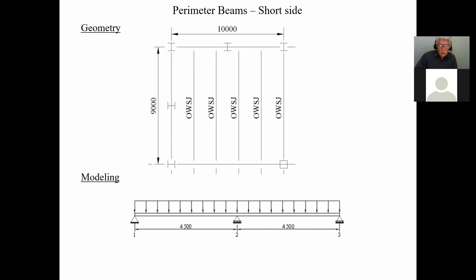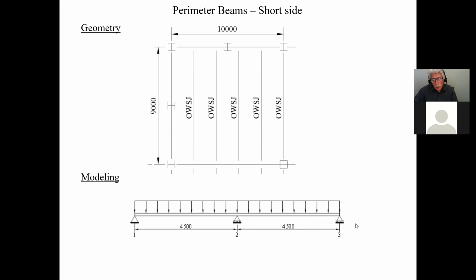As a matter of fact, if you guys want to play around with it, I do that sometimes. I put pin, pin, pin, and then I don't put fix. Fix will definitely have a big change in the results. But if you put pin, pin, pin versus a pin, roller, roller, then you'll see the values are very, very similar. Anton, you have a question?